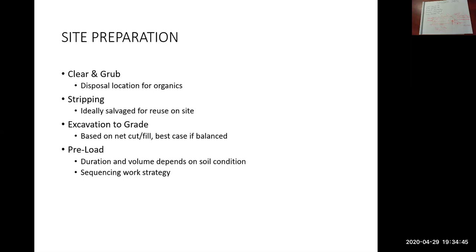The geotechnical engineers on a project will know that there's soft, wet material that's deep down underneath where the road's going to be built. They sometimes require you, the contractor, to preload this area. So they will tell you to build embankments. You're placing fill, typically sand, a certain number of meters high. It could be 3 meters, could be 5 meters high, across the entire road footprint. So full width of the road times the full length of the road at the height that you're directed to.